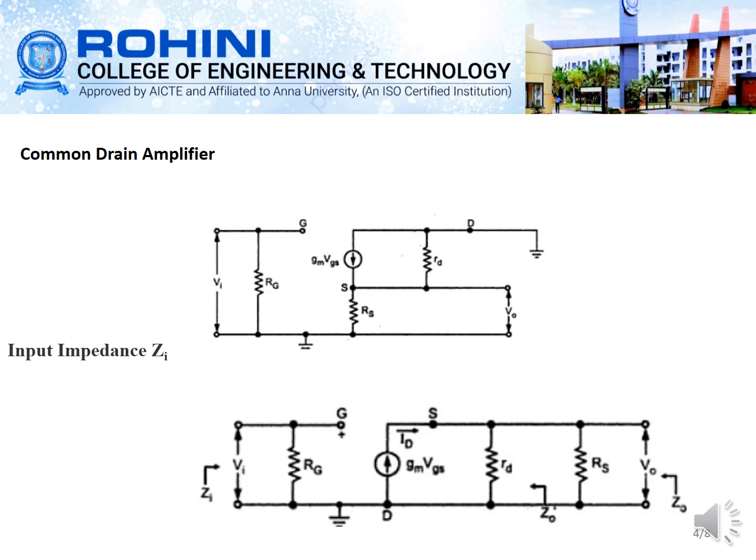And you can see the common drain amplifier diagram. This is the hybrid model for this circuit. You can see Vi, Rg, and this term Gm into Vgs. Since we are considering the source as the output, we will be considering this Rs term in the output region. Here also we will be calculating the input impedance, output impedance, voltage gain, and the current gain.